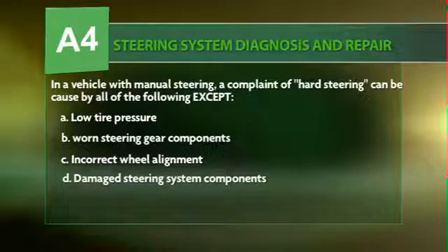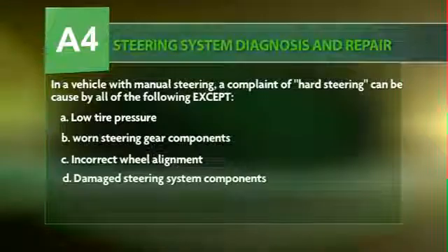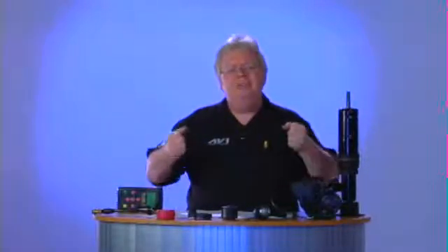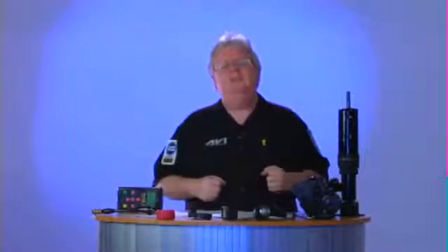If a steering gear component is worn, that means it's loose, and that means maybe the steering characteristics are going to feel loose. It's going to maybe wander, or you're going to give an input to the steering wheel, and it's going to be delayed in how much the car moves to the left or right as you turn the wheel. But certainly it's not going to cause hard steering, the difficult to turn steering wheel.